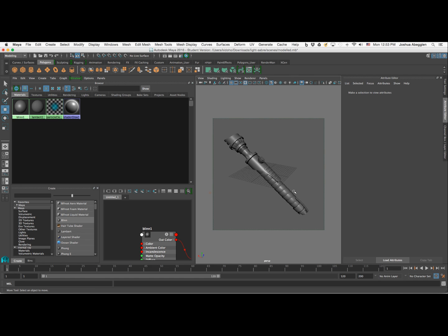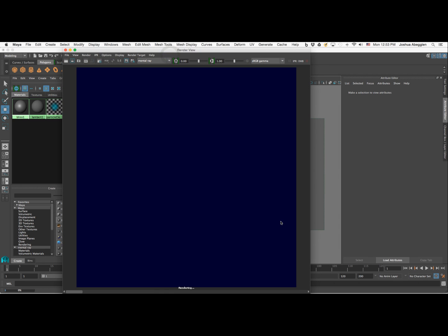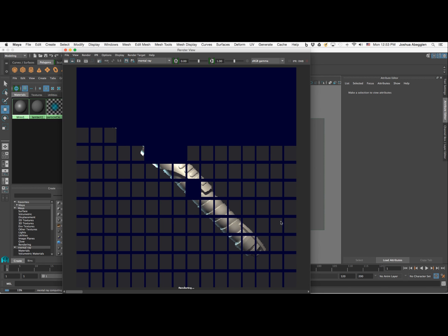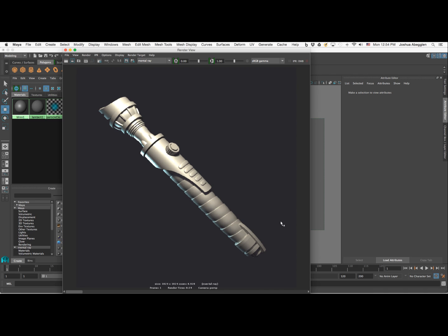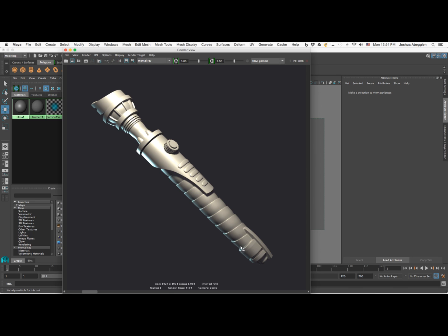We have a different highlight on it now. I'm going to do another render of this object with a specular Blinn material applied to it. All right, and this was the outcome of that specular Blinn material. So go ahead and save that. You can scrub back and forth between the Lambert or matte material and the specular material, and you can see a much more pronounced highlight right in here, especially through the cylindrical portions of this object. Also in some areas, you'll begin to actually see a reflection, as we're seeing right down in here and on some of these flatter, more planar portions of the model as well. So it also has a fair degree of reflectivity, which is part of this default material.